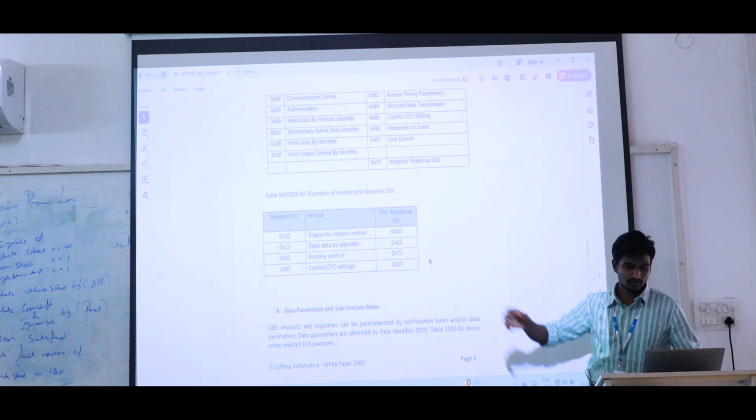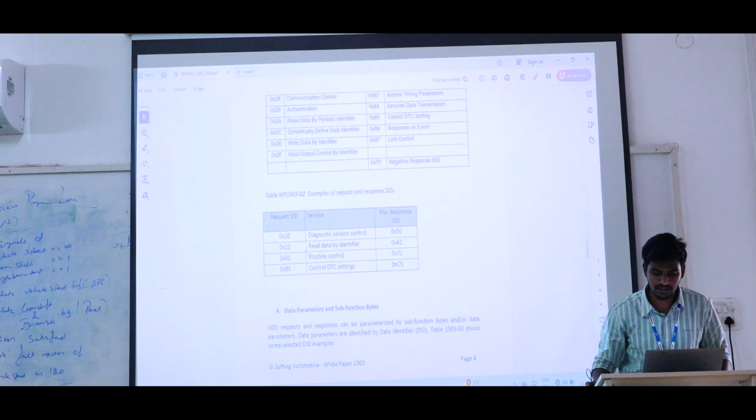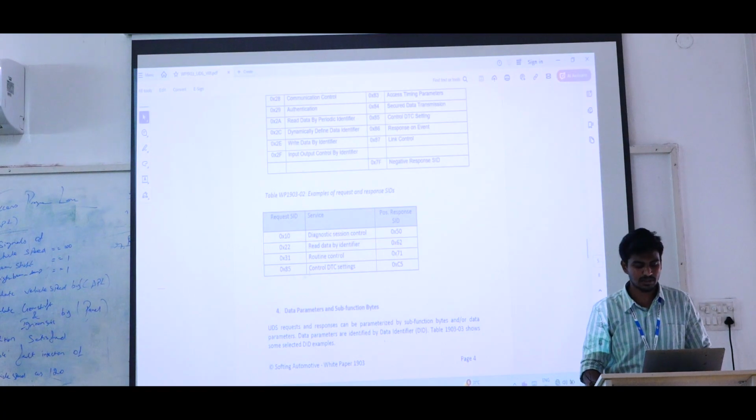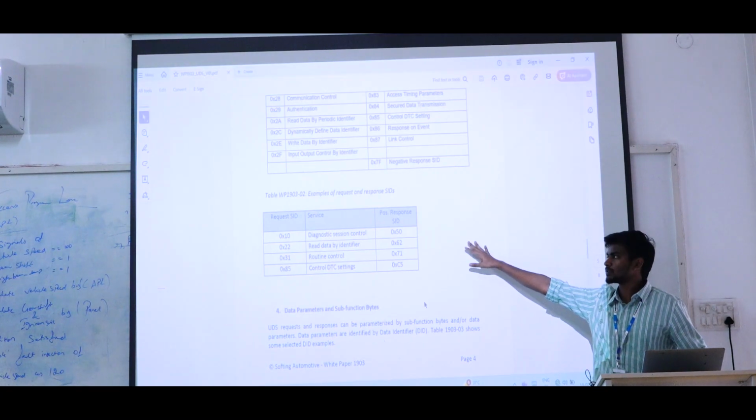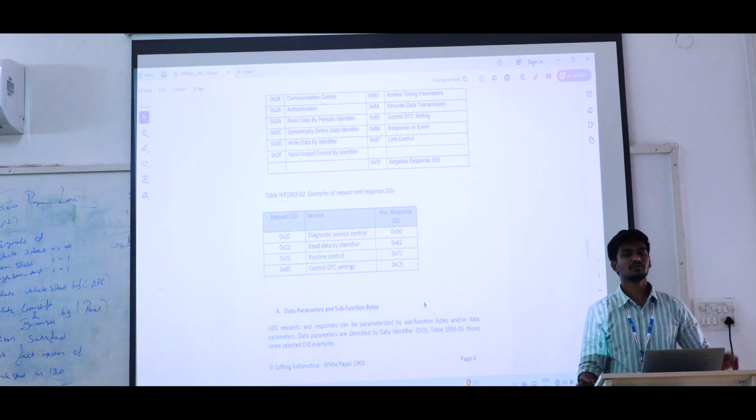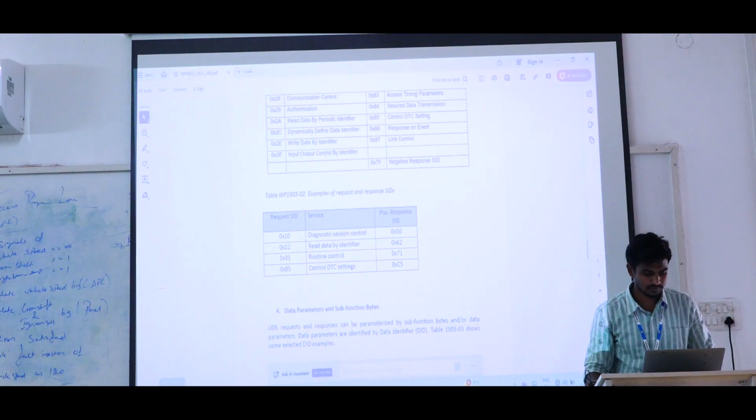Okay. So for example, if you send 22, you will get 62. 31 means you will get 71, 85 means you will get the corresponding value. So whenever we get the additional 40 in the response, that response is called a positive response. So we are able to do the diagnostic here.